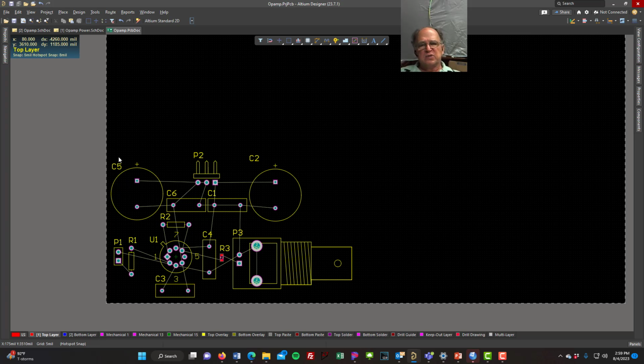I'm a little worried about this footprint though. Look at that thing. Did you ever get an op amp in one of your kits that looks like that? No. Well, they do still make that part. It's usually a military spec part. They call it mil spec. It has higher tolerances. It can operate in colder temperatures, hotter temperatures. It's more resistant to higher and lower voltages, higher precision and all that, but we're not using that in our project. And when I look at this, I'm like, man, that's the wrong footprint. When you see that actual part, it looks like a little water tower you see like downtown Gainesville with a water tower. There's a round can with a bunch of legs coming out.